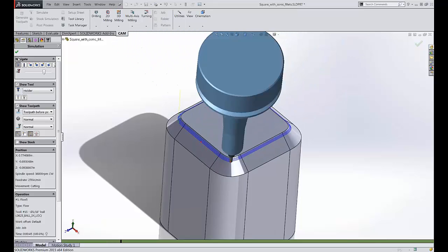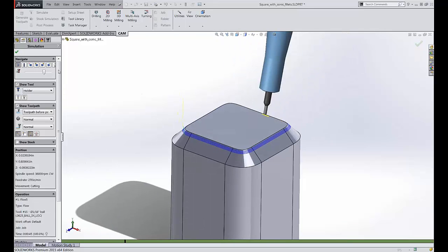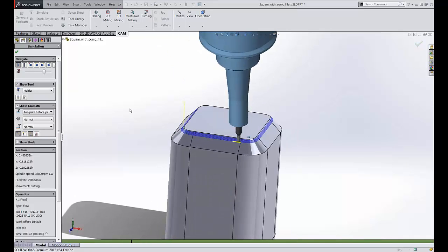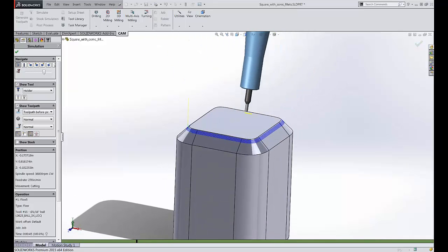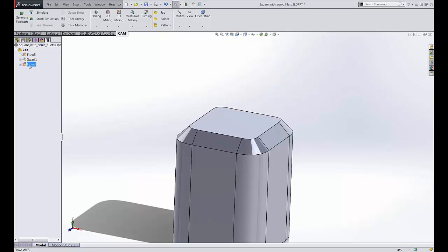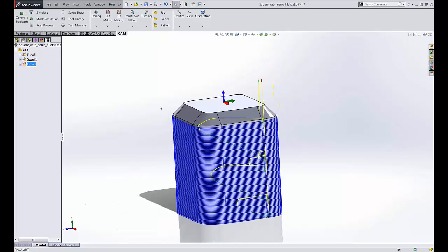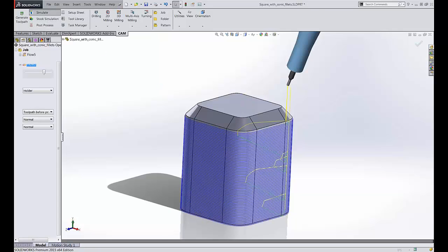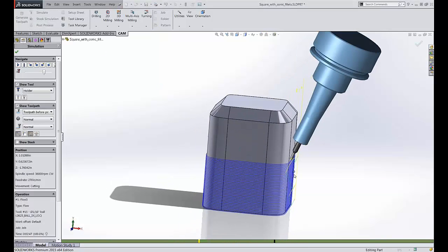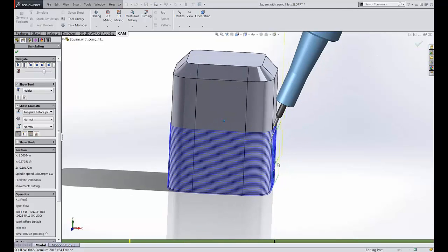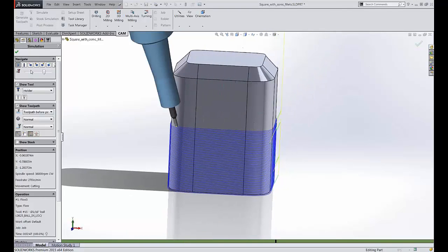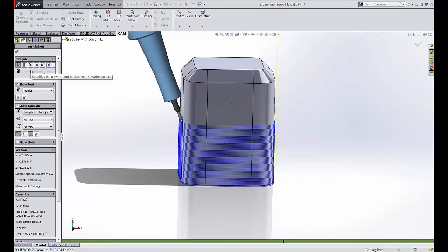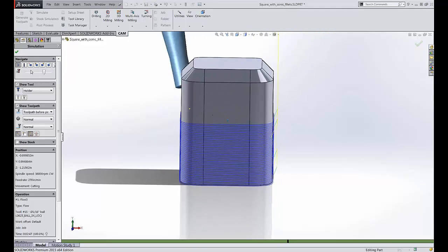But we're starting to get some 5-axis toolpath. This model is not really going to give us much because there's not a lot of curvature to it. We're just sort of going to maintain normal. But I think that it does do a good job of showing an example of how far you can go. This, I think, is actually the same thing that I used in my slide deck. By just applying some tilt and maintaining normal to the surface, you can see that we're able to tilt that tool holder out of the way.